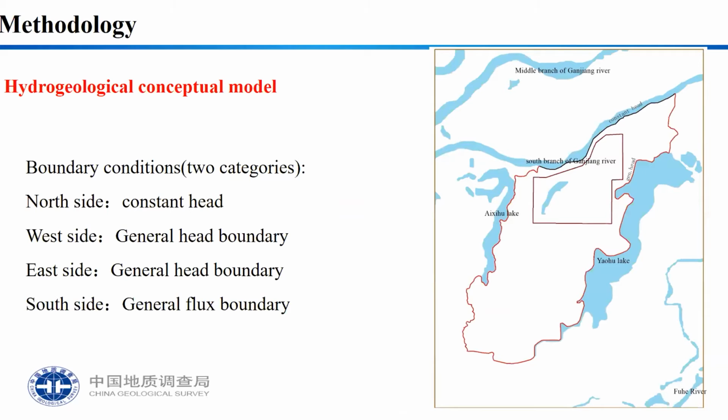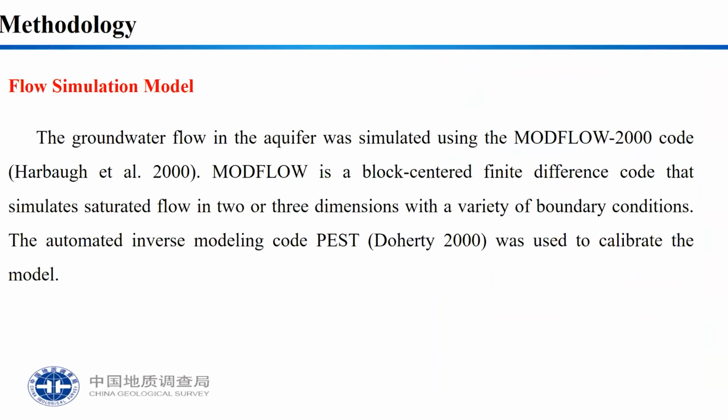Methodology, hydrogeological conceptual model. In this work, we set the boundary conditions into two categories. The north side is the specified head, and the east side and the south side are general head boundaries. Flow simulation model.